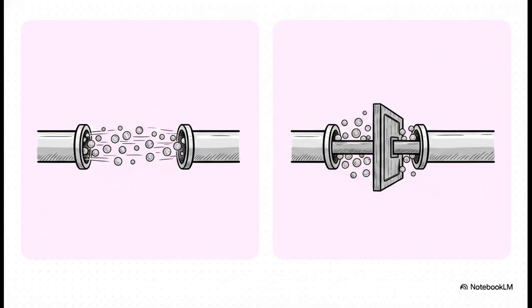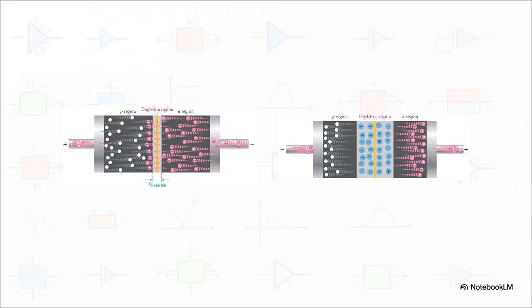But what's actually happening to the silicon inside when we do this? Well, there's this fascinating internal tug-of-war happening here. In forward bias, the external voltage repels free electrons, shrinking that depletion region and giving them enough energy to cross over. Boom. Current flows. But if we flip the voltage into reverse bias, we essentially pull those electrons away from the junction. That depletion region widens into a massive barrier, and the valve firmly, completely shuts.